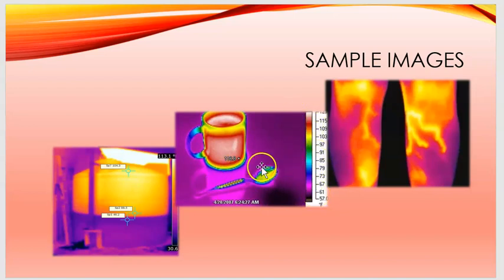And you can also see, and that's an interesting one right there, where you see the spoon. It's right there on that tip. It's probably not actually that hot. When you look at this scale, it's probably not actually up into the 115. It looks like somebody just took a hot tongue and licked only half of it. What's happening is a shiny spoon has low emissivity, and so it's probably reflecting the heat off of this cup. And hopefully that's kind of a precursor to what's going on with emissivity.